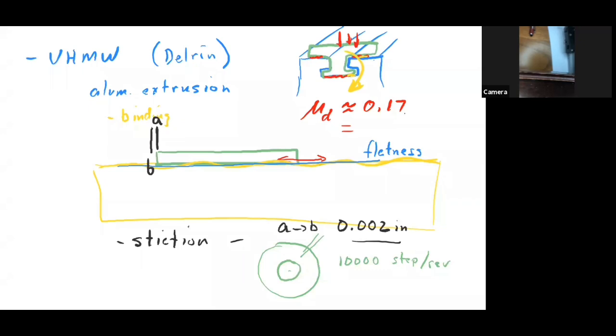It started to feel the pull, the magnetic spring was starting to pull it. But if there's a tiny bit of friction in here, it didn't move. You give it 2 microsteps. Now it's starting to extend that spring a little bit. 3 microsteps. Somewhere around there, maybe 4 microsteps, it went broop.